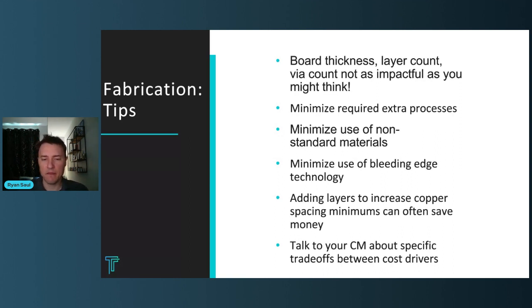And then finally, oftentimes we'll have engineers who are trying to make their board less expensive, avoid potential manufacturability issues. They'll add additional worse manufacturability issues. So for example, we had a customer recently who was trying to avoid epoxy filling their vias and plating them flat, which they otherwise would require, by making an unbalanced stack up, meaning adding an additional single layer on one side that would get no drills. And that is doable. You can do that, but it's much more expensive